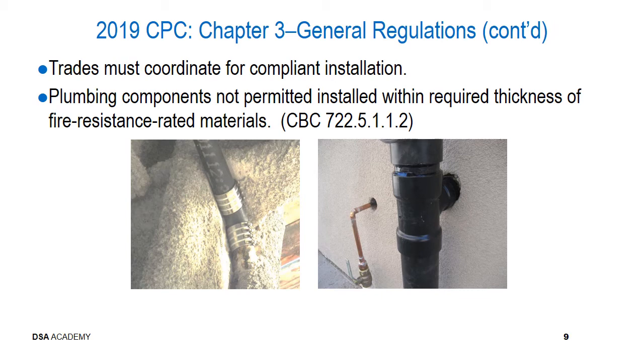The image on the left shows a routing for what appears to be 3 or 4 inch cast iron pipe, hubless, joined with some Husky bands. It appears that the bottom section of the pipe was in place at the time of the application of the fireproof spray.